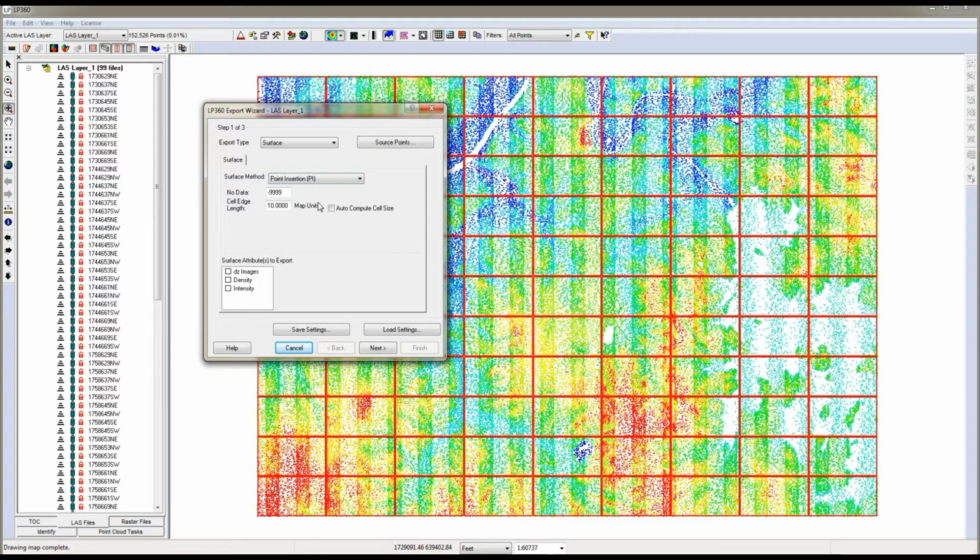Okay, what are the points that we're going to use as source points? In this case, we don't want to count every single XYZ point that's in the LiDAR point cloud because some of those are secondary returns. So for point density, we're really only interested in how many original shots were there, how many LiDAR pulses, and did the pulses meet the point density requirements.